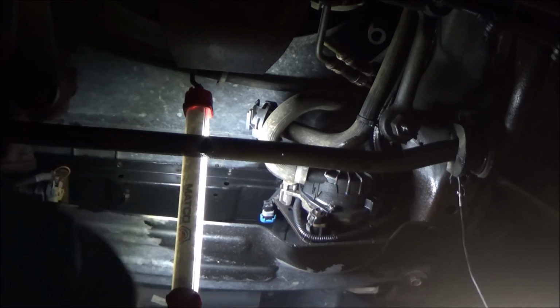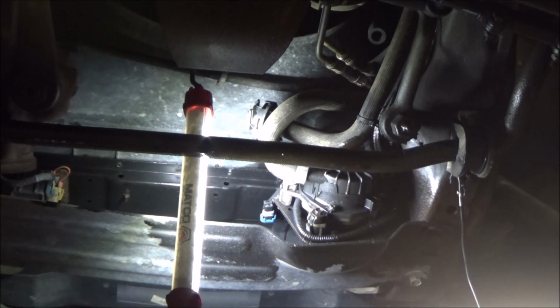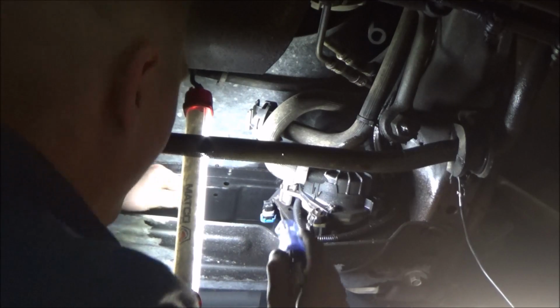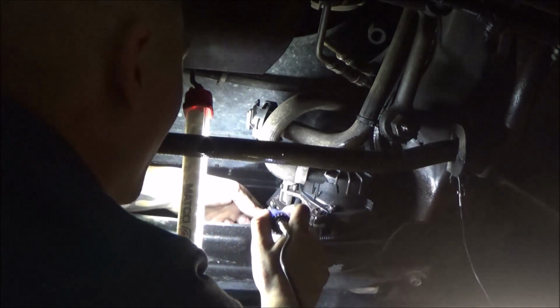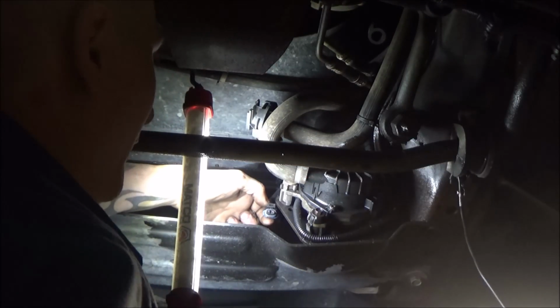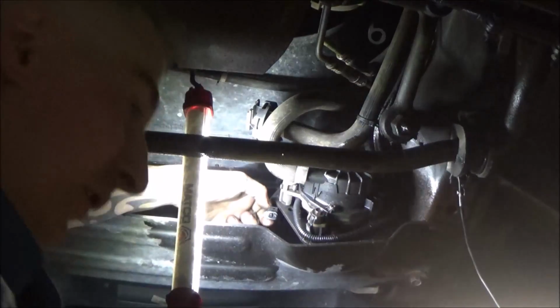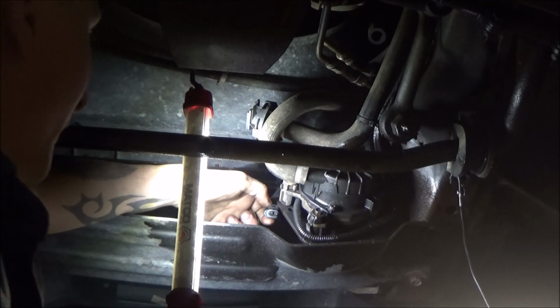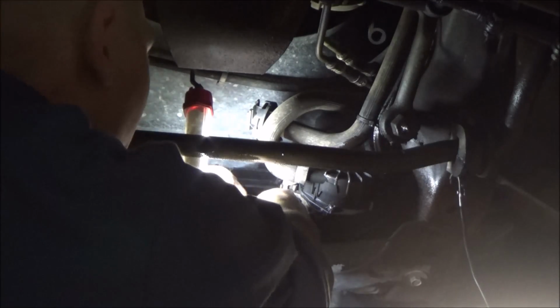So I'm just going to get a T-pin here, guys. Let me see if I can find one. Yeah, so I got a T-pin here, guys. And what it looks like on this connector, I'm just kind of front probing this one more time. This terminal to the left of you guys, I'm not really sure how well you guys can see it, but that's our power feed for this.